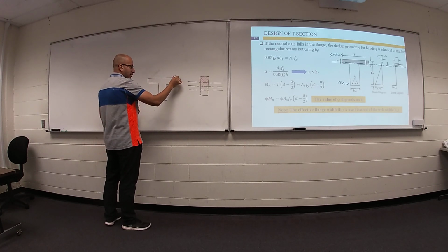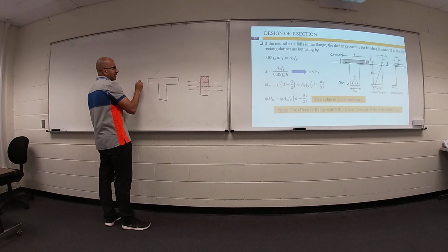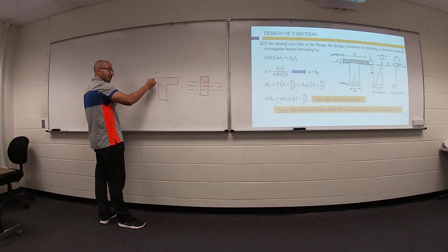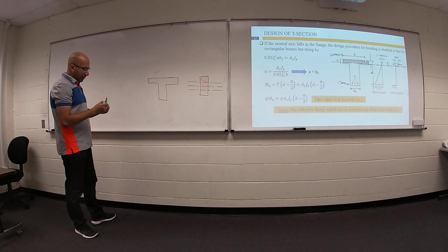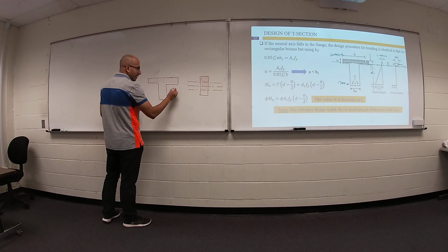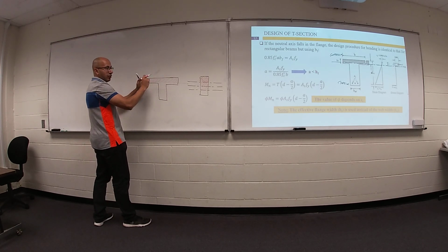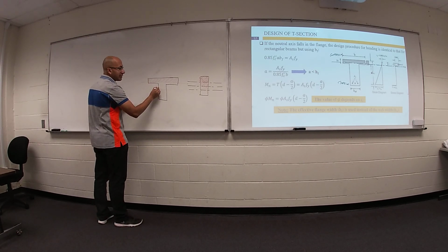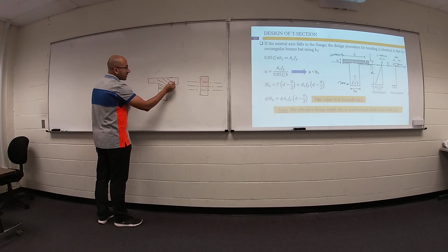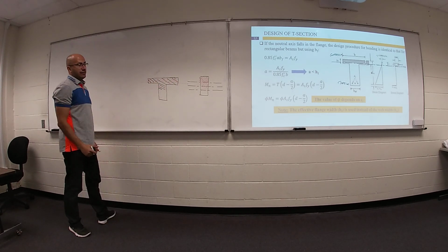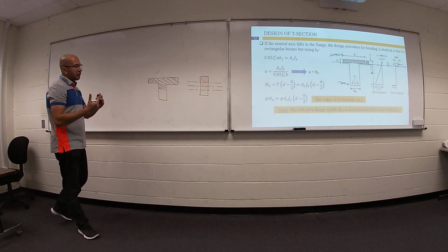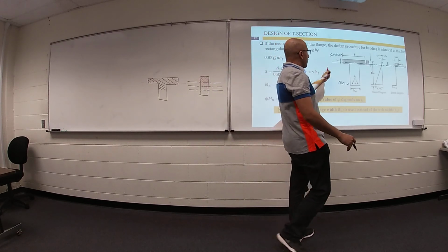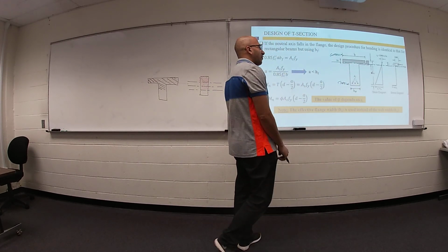big difference between your neutral axis is here because this part is a big rectangle. That's fine, but it's rectangle. But if your neutral axis is here, your shape of the cross section above your neutral axis change. We have something like this. It's not rectangle, something else. So, big difference between your neutral axis in flange or neutral axis below your flange. First case, we will assume your neutral axis in flange.